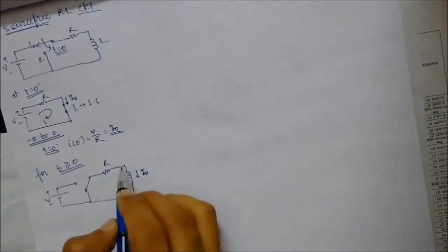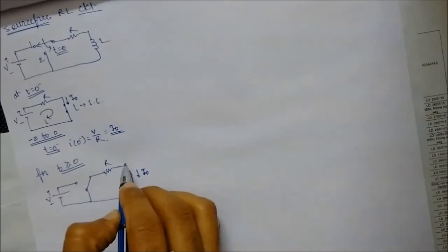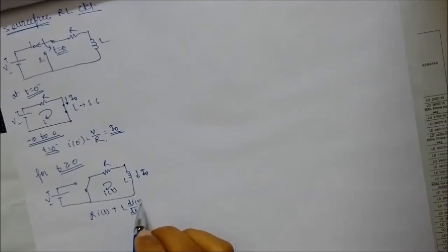Hence we say that it is a source free RL circuit. Now let's say i(t) is the current flowing through the circuit. So write down KVL for it: R into i(t) plus L di by dt is equal to 0,